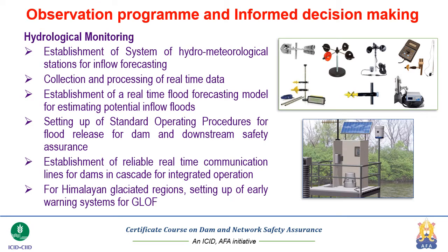Observation program in informed decision making. Now this is an ingredient which is largely associated with the dam operators. There are multiple types of observation programs. One of the main programs is hydrological monitoring, where the inflow floods are related, where the establishment of a system of hydrometeorological stations for inflow forecasting becomes a must, especially for the large dams and those dams which are also located in a cascade, with large catchments behind them.